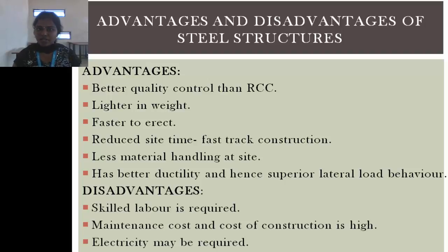The basic advantages of using steel in the structure are better quality than RCC, lighter weight, faster erection and faster construction. Less material is required, and steel has better ductility and good behavior against lateral load application. Coming to disadvantages, there are a few disadvantages in using steel structures.